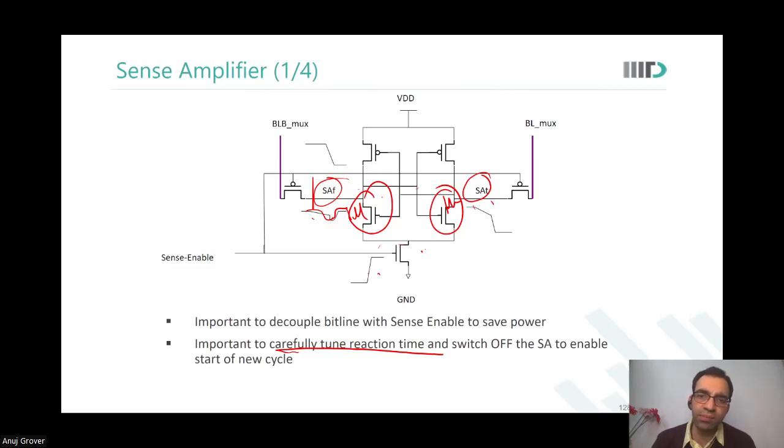No, sir, we are not storing any data. Is there a stability condition around the sense amplifier? No, sir. Okay. See, the structure looks very similar to a 6T SRAM cell, but don't get confused. It's still a sense amplifier. It has a completely different functionality. To design it, you need to consider the functionality that is required of it in your analysis, not how it appears to look.